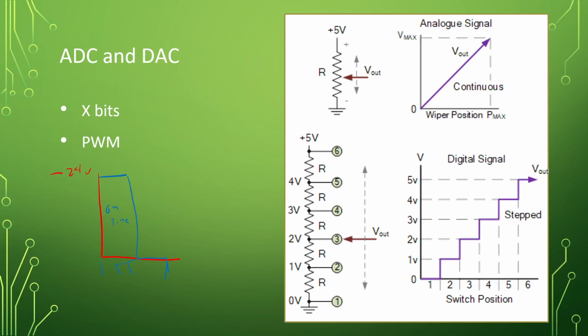All right, so we can actually turn it on and off really quickly. Now, a lot of PLCs, you might need specialty hardware to do this. Our relays aren't going to click fast enough to do this well. You need solid state transistor outputs to transition fast enough. If you're even trying to play that game, it's probably not the right game to play with a PLC. You want to buy a digital to analog converter to actually do this, so we don't have to worry about that pulsing thing. So, a lot of games that can be played there.